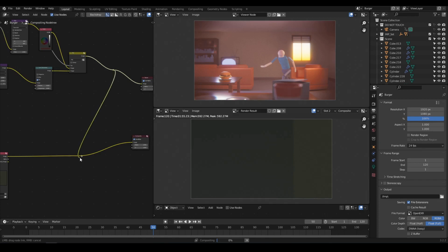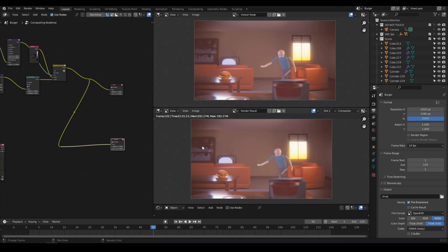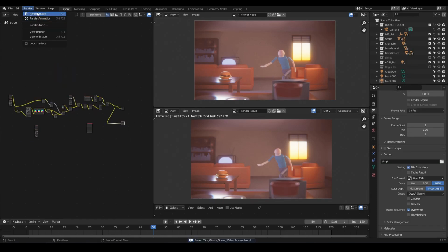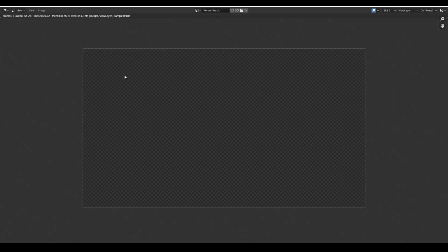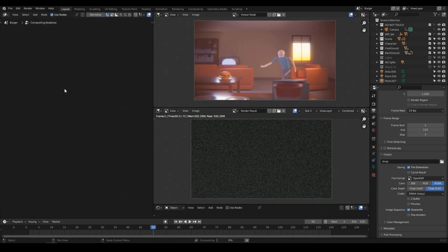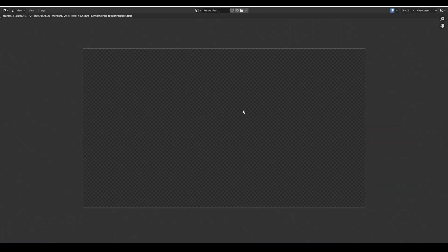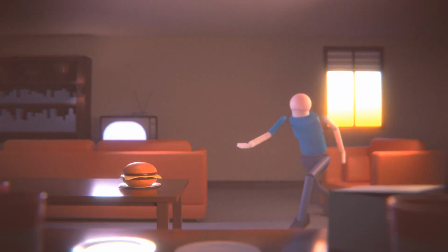I'm also gonna use an image sequence for the same reason I did earlier, and now it's time to render it. You can see here, if I launch the render, it's gonna take a lot of time and calculate the actual scene. This we don't need to, because we are basing our renders off of an image sequence that is already existing. So if you remove here the node render layer, you will see that it's going much faster because it's not rendering the scene but just actually calculating the compositing. Okay, and here is the 80s look image. Okay, so hope you like it.